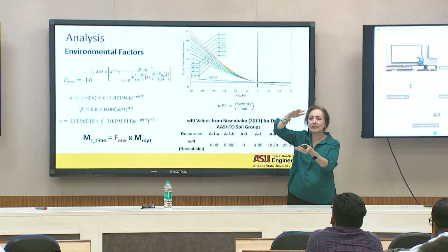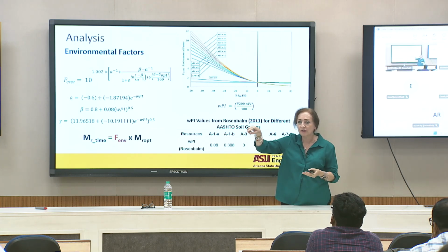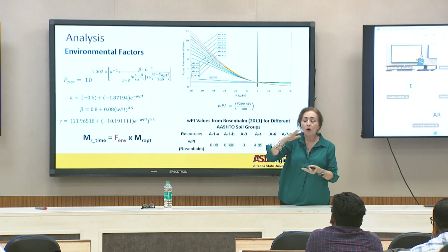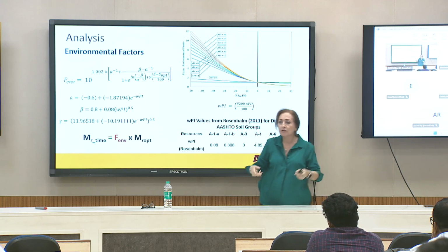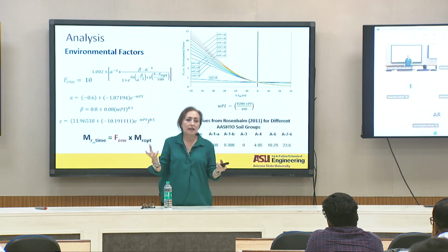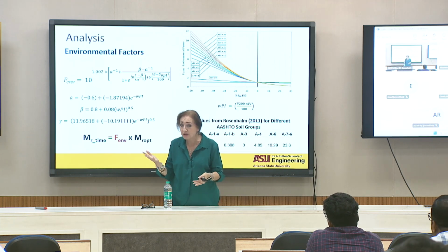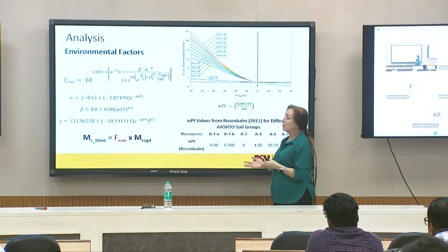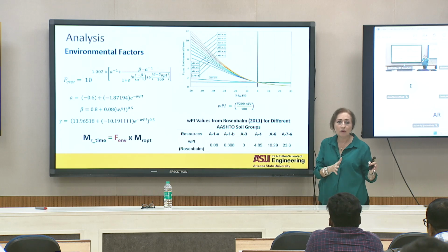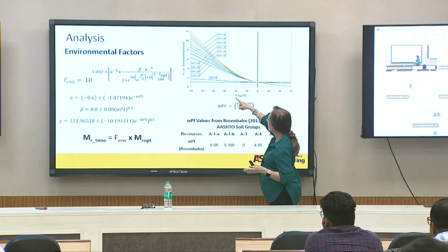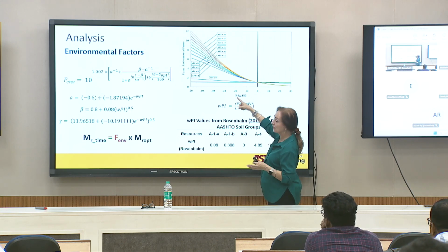Usually granular base material is compacted at optimum condition, or plus or minus, so you got this value. Or if not, you're going to have to do some coring and figure out what the density is before the flooding to figure out your degree of saturation. But we do have data before that, which is the initial, and now you got, with time, a change in degree of saturation.